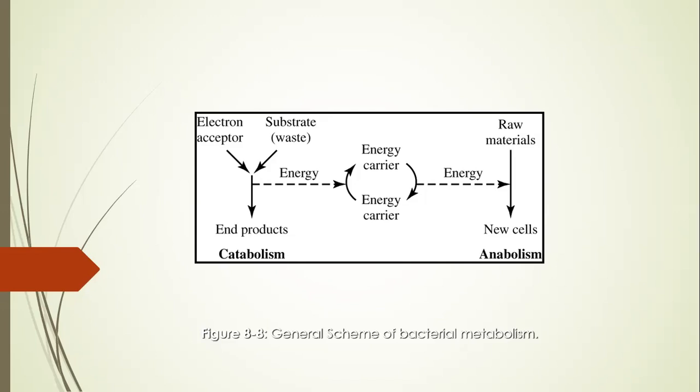So now these are the waste components that have been converted into new cells; using the substrate, more cells are generated. So this is how basically we get rid of the organic waste in wastewater, right? The new cells will be settled down in the second treatment, and you separate the good quality water.